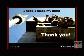If it's constant, that's what you saw, the results for constant airflow. It will vary a little bit with wind speed, but I'm looking at the design case. So I'm looking at the 1 year response for acceleration of the building. What's the 1 year return period wind that causes the response that I'm after to design for? I'm going to inject flow at that speed, and it's the ratio of the injection speed to the wind speed that's important, the blowing ratio effectively. It's a non-dimensional parameter. But it's a good question, and what we're going to do is pulse the flow. This is what Boeing will be trialling on the vertical stabiliser, the tailplane of their new 787s: synthetic jets. These are little flat discs with slits in them.